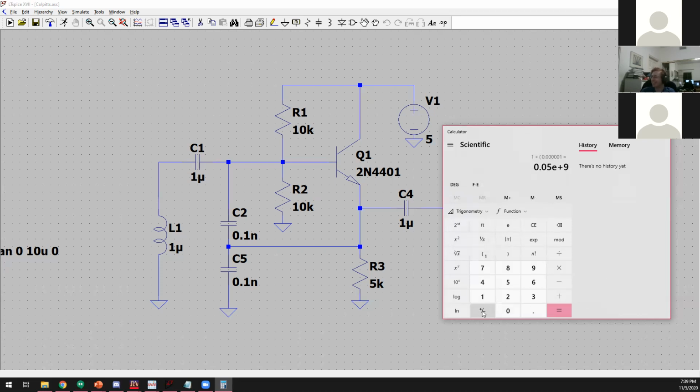All right, thanks. All right, so we're doing the inductance times the capacitance. Thank you for your participation, by the way. And we'll take the square root of that and take the reciprocal of that. And that's omega naught. Now to get the standard frequency, we got to divide by 2 pi. And I messed up because now we're getting something times 10 to the minus 9.